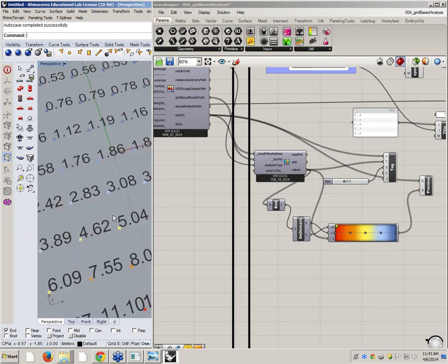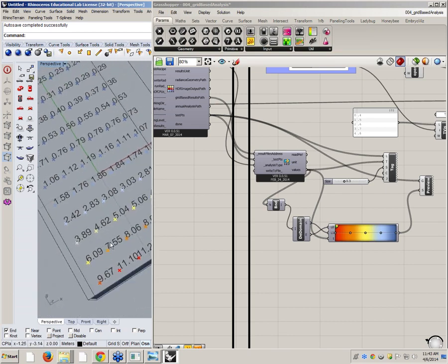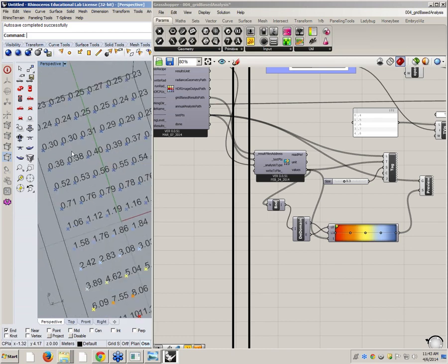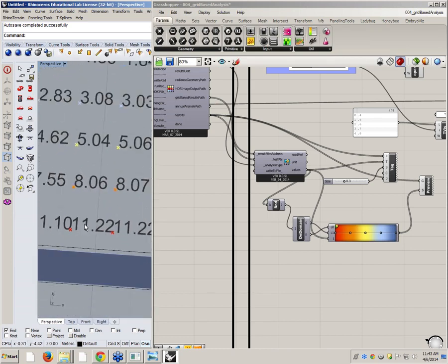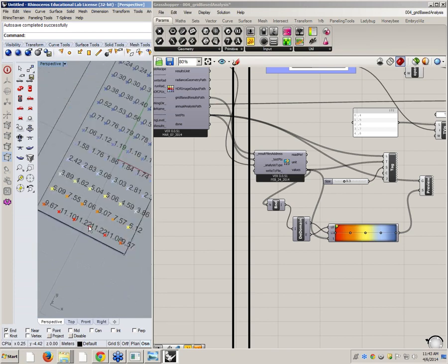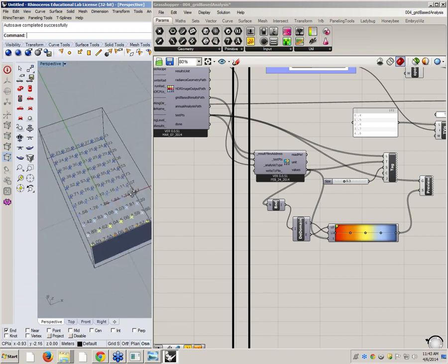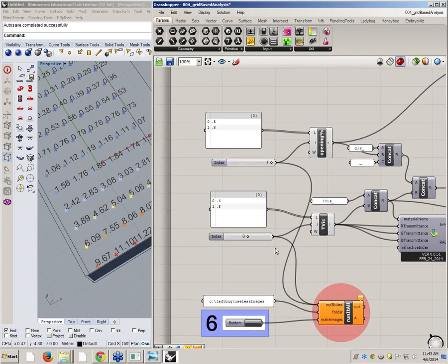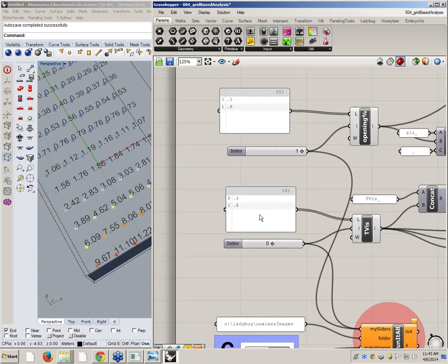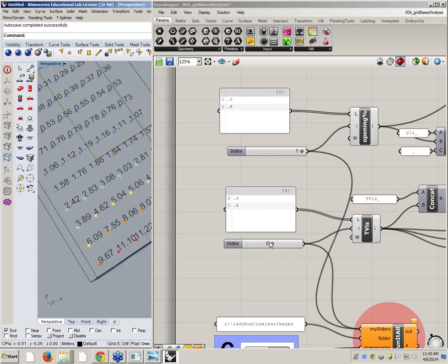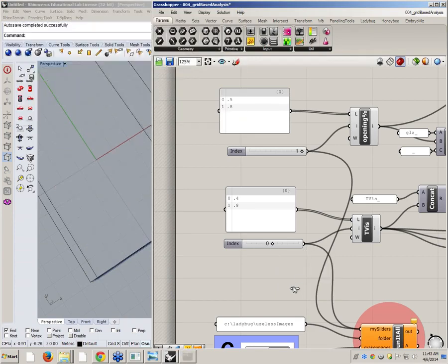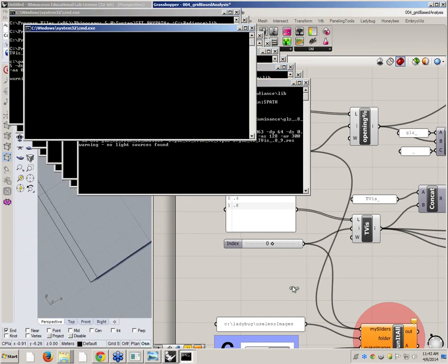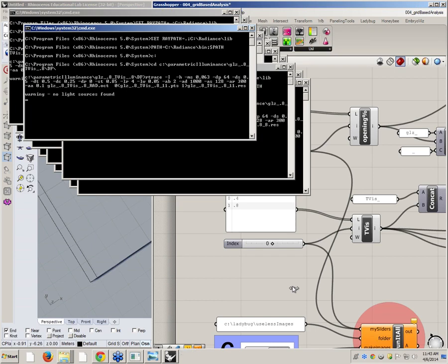So now you can go and read the values, right? 3.8 here, 8% daylight factor here. And did we select the dark glass? Probably yes. So that's why the values are this low. I did select the first one, which is 0.4. Now just go ahead and change 0.4 to 0.8. I just changed it to 1. What will happen is it will rerun all the analysis.